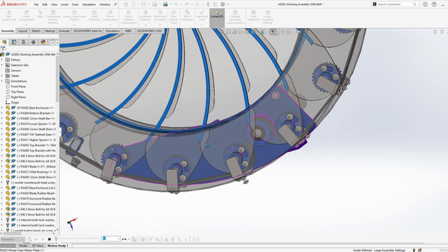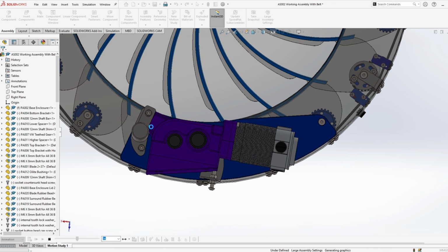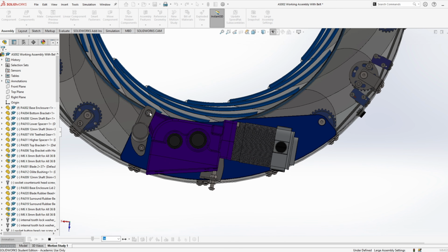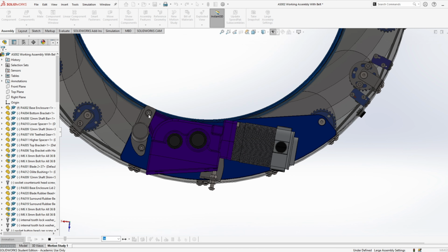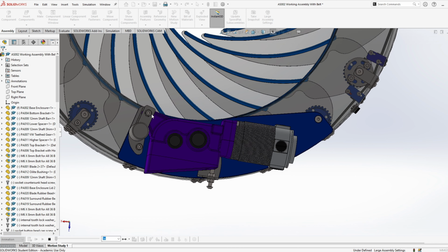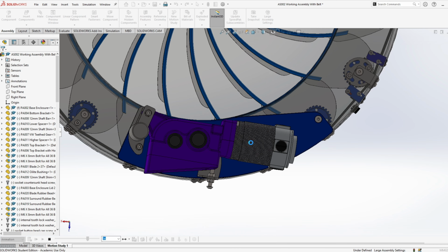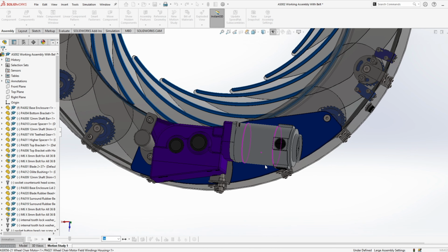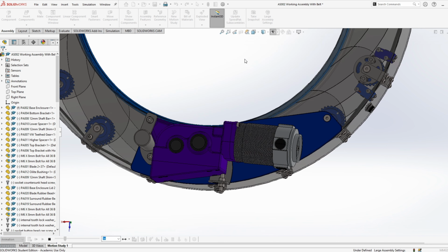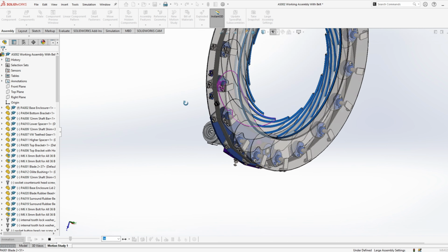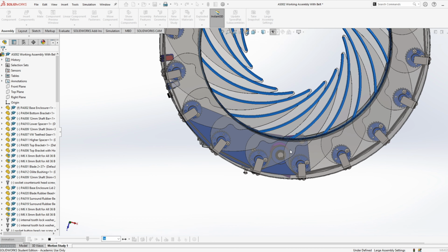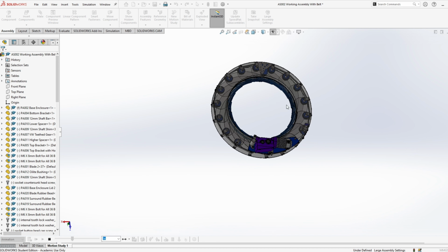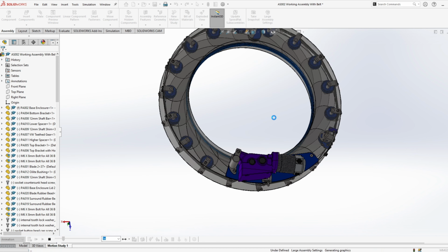If I go round to the front again, I have the gearbox mounted at this point, pivoting here at this bolt, this Allen key head. I think it's an M10 bolt as far as I mind. If I were to grab the back of this motor and gearbox and move it in towards the centre of the aperture, I would in turn be tightening this belt. So that's a really unique way of tightening the belt without using additional tensioners.